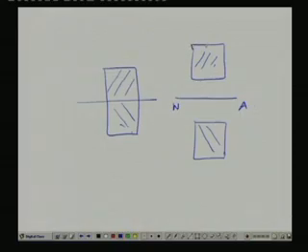So, what we understand is that if we keep our material much apart from the neutral axis, then we get a higher value of section modulus Z. Better value I mean to say is that it will be better for the stress levels. That means the stresses in the machine members will decrease.